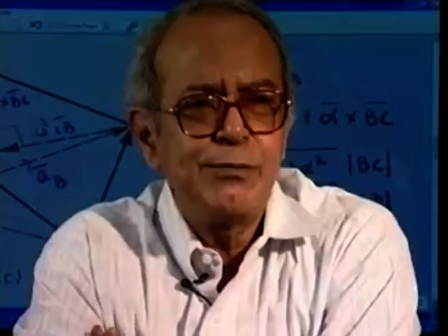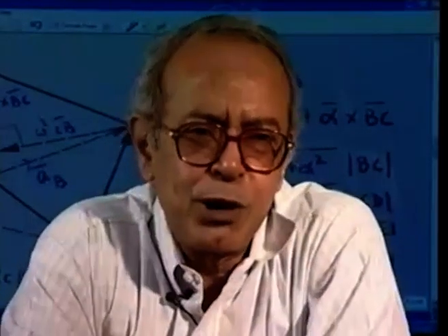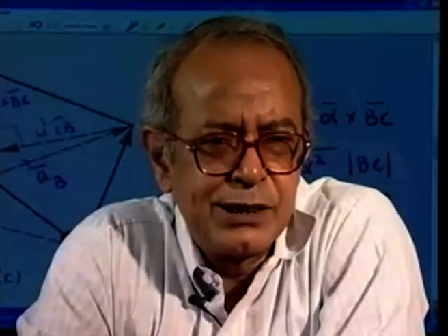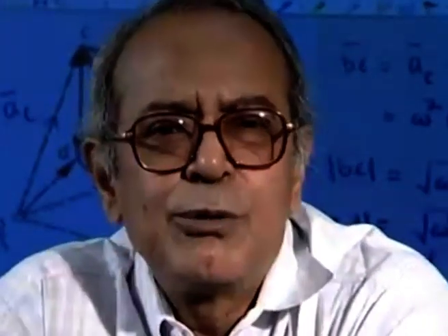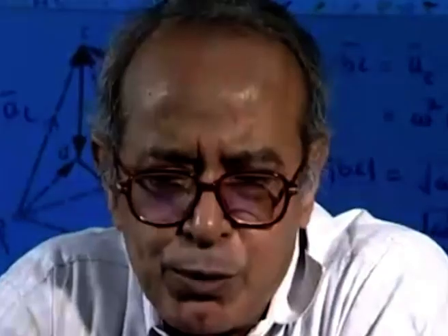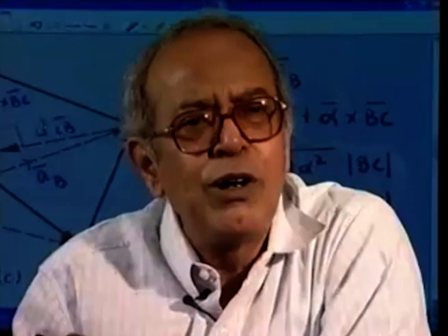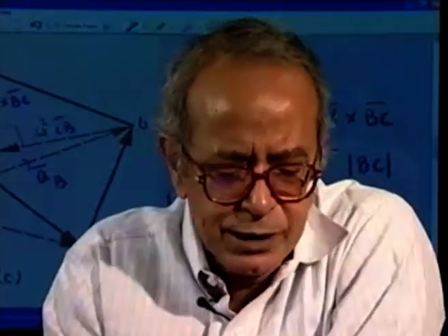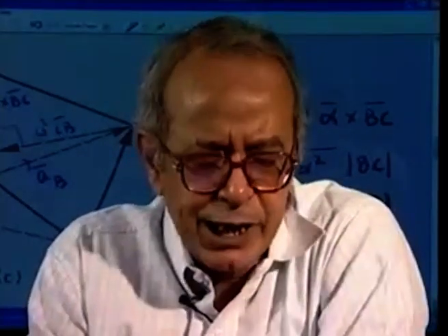At this stage, let me now summarize what we have learned today. We have just started the process of velocity and acceleration analysis of planar mechanisms by drawing velocity and acceleration diagrams. We have seen that we have to start from the input end, where the input motion characteristics like velocity and acceleration are given, and then go successively through all the motion transfer points to reach the output end, where velocity and acceleration have to be determined. We have shown it through an example of the slider crank mechanism.